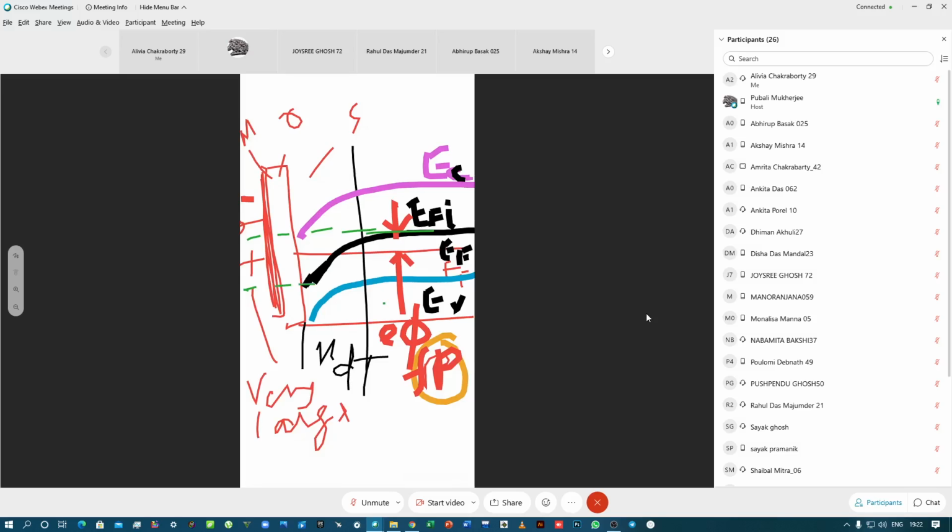The distance between the intrinsic Fermi level in the bulk material, you call it bulk because it is far from this interface, and the intrinsic Fermi level at the interface, this magnitude, is called the surface potential, or E phi s.